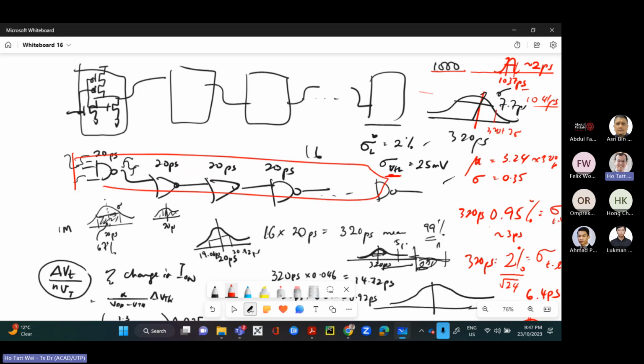So this is why I'm emphasizing that process variability is really a challenge. And this is the case especially when you have chips where you don't have one very dominant critical path, but you have many paths that are about the same delay. As you can see, in this case, I'm just looking at a chip where I have replicated compute units. Each of them has roughly the same delay, 1,000 of those replicated units like a modern GPU. And all of a sudden, your max delay is almost more than 3 times the critical path of a single chain. And this is only due to process variation.